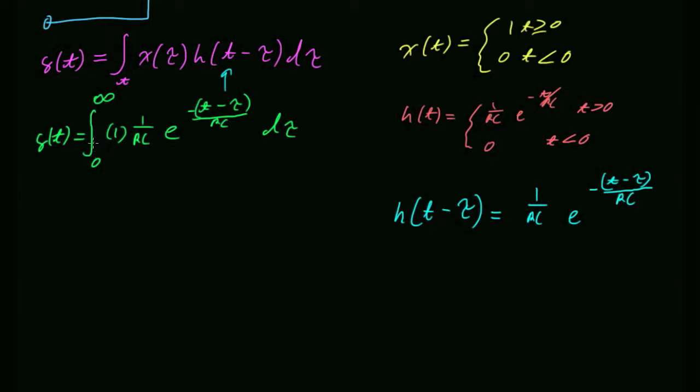Our input starts at 0 time. Our impulse response starts at 0 time. Therefore, when you're looking at those scaled and shifted impulses, there are no scaled and shifted impulses that occur before tau equals 0, right? There's no system, there's no input, sorry, before 0. So there are no shifted impulses at negative times. So we only need to integrate over positive times. But we do need to integrate over all positive times. So we do have to go out to positive infinity.